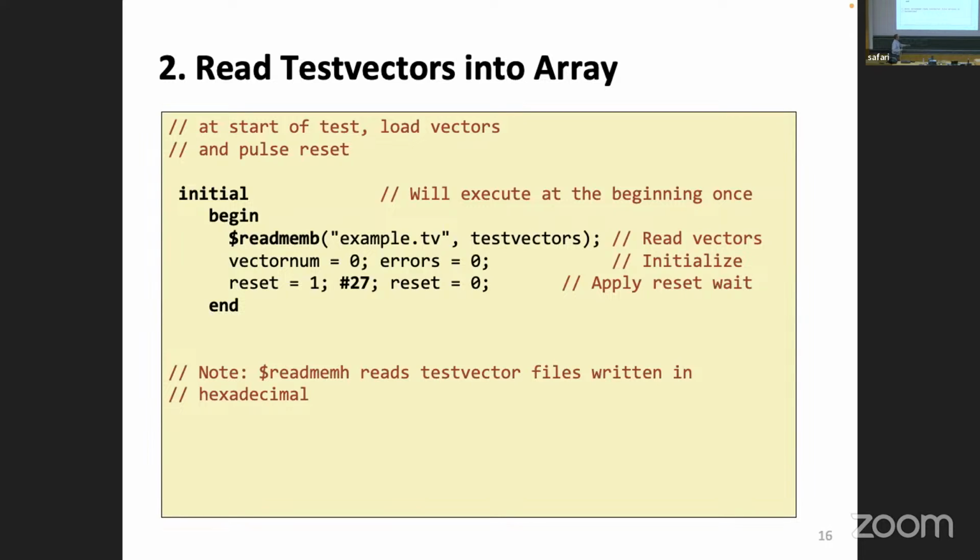Because at the same time as you are letting the flip-flop work and saying you are no longer in the reset state, now you can wait for the clock. The clock came. Did I release the reset first, or did the clock come first? Let's not go into this debate. You can have any time you want, just release the reset, but not exactly at that time, if you please. Does that make sense?